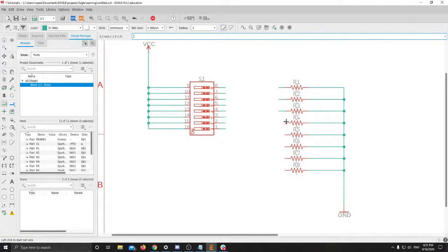This is basically telling Eagle that we actually want a net here, connected to that part, but we are going to connect them by naming them like we just talked about instead. So what I can do is click this label tool on the left, and there are two options in the top: XREF off and XREF on. This one gives you a little tag when you do it, like this, whereas the other one will just show you the name on a line, which personally I don't like. I like having it in the little box, but it's really up to you.